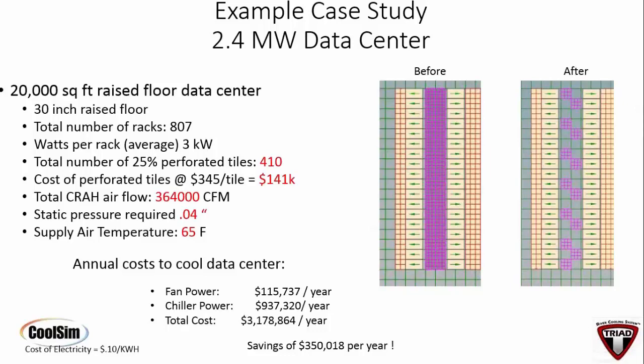Right. What we see in live studies where they're doing thermal imaging is that one panel actually fans out while it's directing air to the face of the cabinet. It fans out across the cabinets on the two sides of where the panel is located. So it actually does cool three racks, depending on the kW in each rack. That is part of the turbulence that we design. That part is very hard to show in CFD modeling.